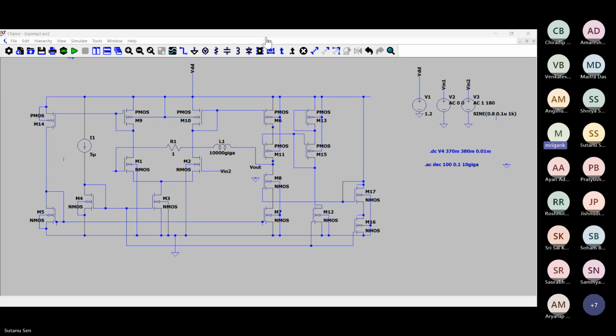So how much gain to have? It depends upon many things. It depends upon the target precision. It depends upon whether you want to have a very high precision gain in the amplifier. You remember that if you make a feedback amplifier, the open loop gain plays a role, right? So ideal gain is just given by 1 upon beta in the feedback amplifier, but it has a factor of A naught beta divided by 1 plus A naught beta.